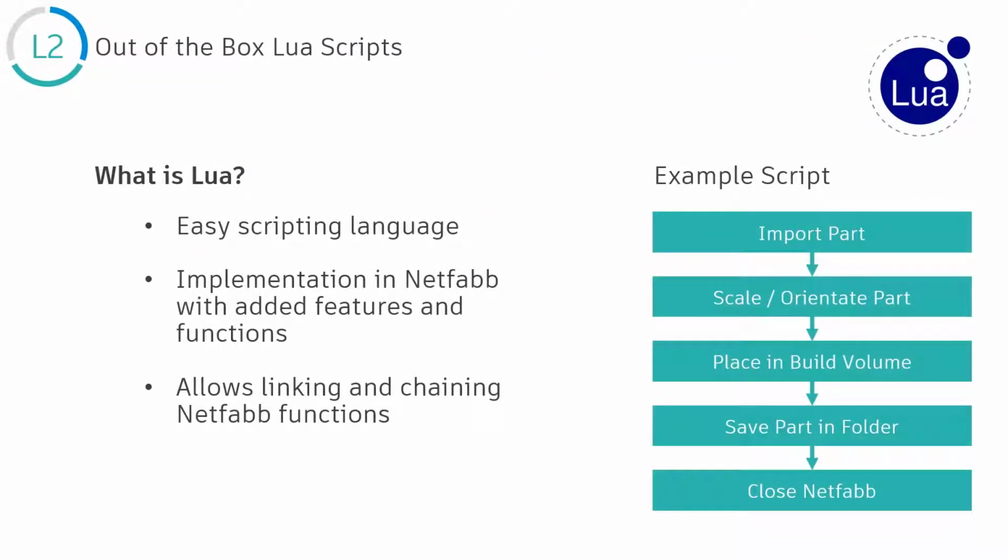Let's have a look at Lua for all of those who have not yet had anything to do with it. Lua is a lightweight scripting language that is fully implemented in Netfabb. Apart from the regular Lua syntax, we have added additional features and functions that allow you to call and link nearly all functions of Netfabb. How such a script can look is shown here on the right. In this example script, a component is imported, scaled or orientated, placed and stored in a folder. Afterwards, if you prefer, Netfabb can also close itself after finishing the script.